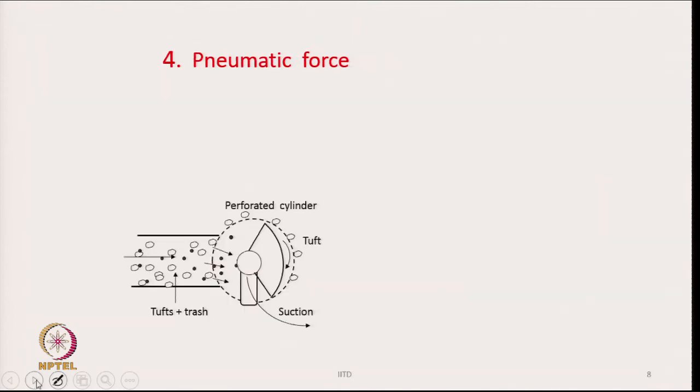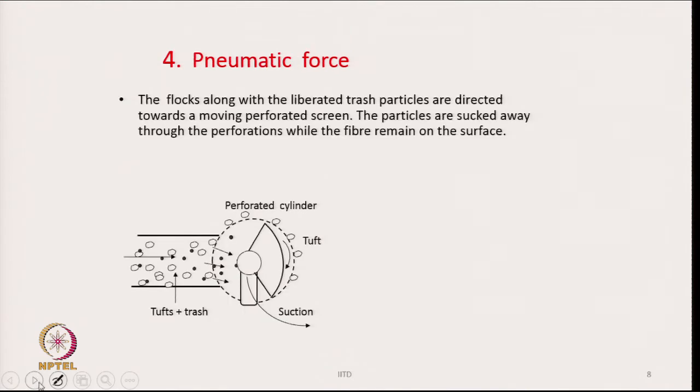Okay. The next force which is acting is a pneumatic force. This also is present in some of the machines, and this is also effective in liberating trash particles. The flocks along with the liberated trash particles are directed towards a moving perforated screen.